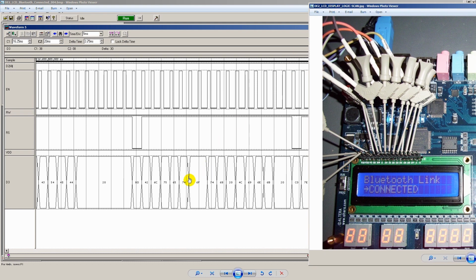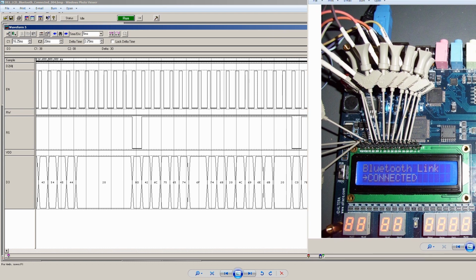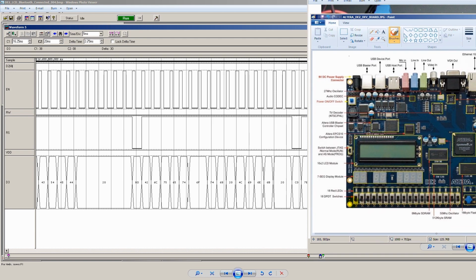The signal lines or variables that I have set up that dictate which hexadecimal value is here are essentially dictated by either a string value that we can write within our VHDL code, or what you can also do is have a specific set of switches on your DE2 board, for instance, the first 8 bits of switches, dictate which hexadecimal value is on the data bus at a particular time.